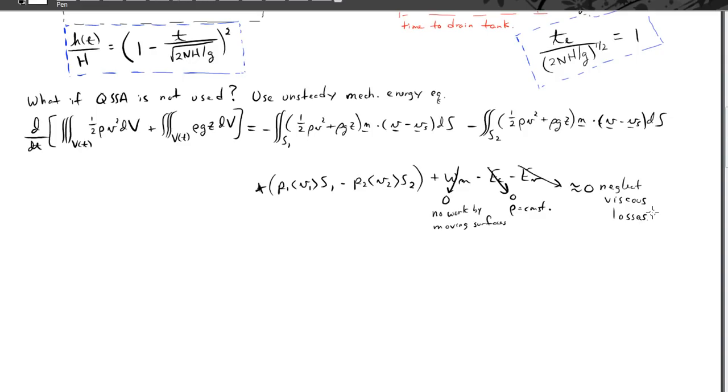All we have is the opening at the bottom of the tank. The water and the liquid in the tank moves downward very slowly. So approximating the viscous dissipation term as approximately 0 is very reasonable for the present situation. Once again, the velocity gradients are small in the system, so we'll assume that viscous dissipation is negligible. So what we essentially have now is the unsteady form of Bernoulli's equation, but applied to this control volume instead of just at 2 different points in the liquid.